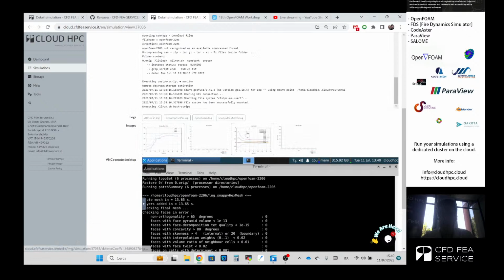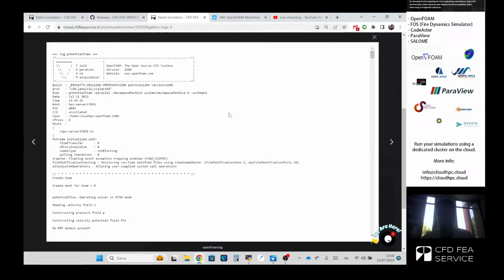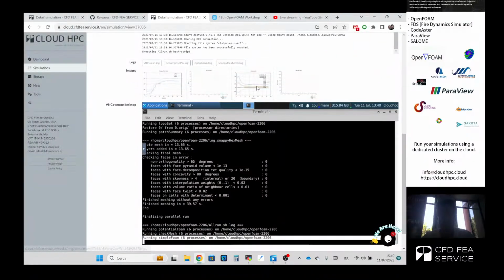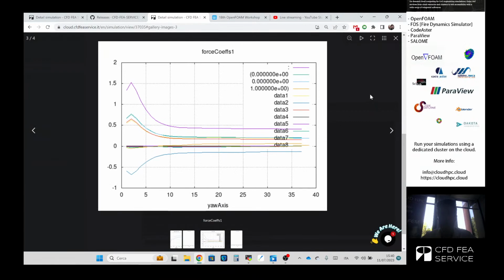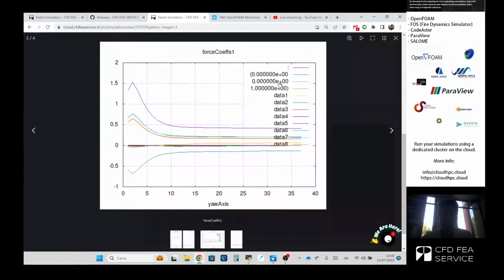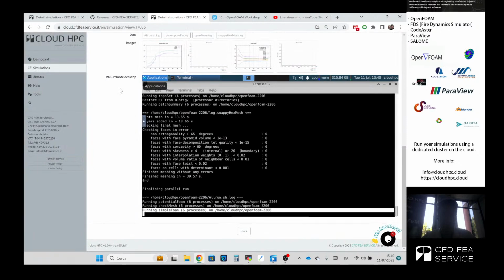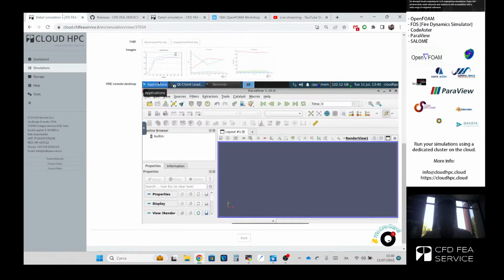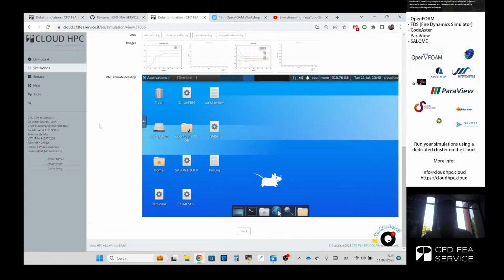You see now another feature is that now that we have simpleFoam running, you get access to all the logs. So in here, OpenFOAM log, I can access the log information of OpenFOAM and check the residuals, but also these are plotted at runtime using the function objects that someone should define in the controlDict file. Yeah, so my simulation is running smoothly. Let's see if I can open ParaView now and actually open the results of this particular analysis. And here Snappy probably is going to finish. So we go back here and we are going to open ParaView.